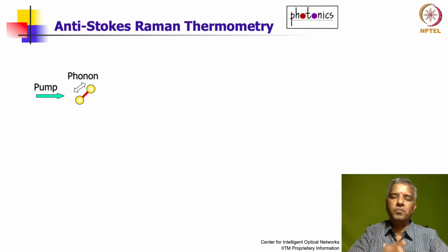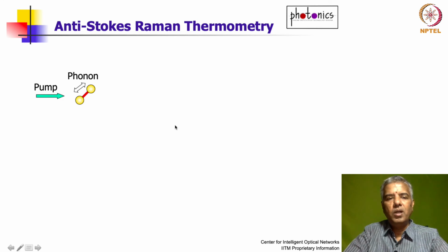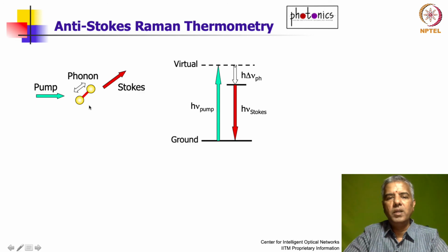Okay, so essentially we need to marry the OTDR concept with something else. What is that something else? That is what we are talking about as Raman scattering. Okay, so what is Raman scattering? As I mentioned briefly before, when you have an incoming electromagnetic radiation interacting with the vibrational modes of the medium, which are called the optical phonon modes, then there are two different events that are possible. One is it can give energy to this vibrational mode, in which case it scatters off with lower energy.